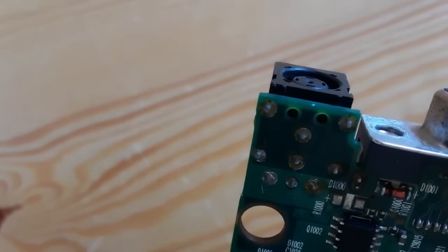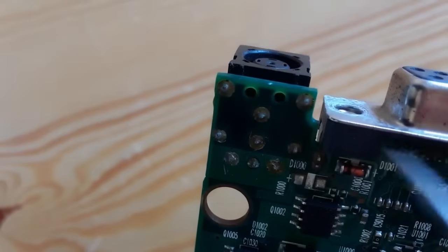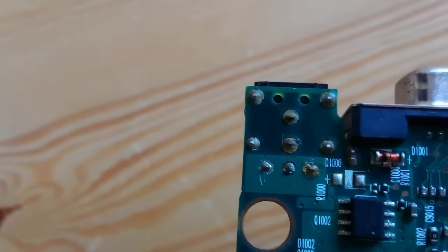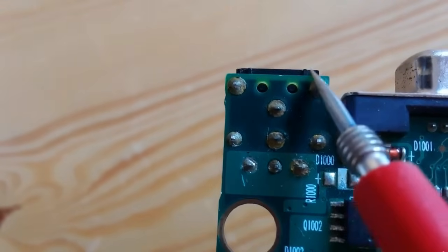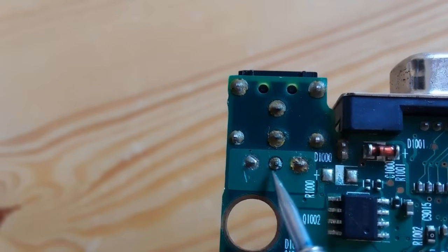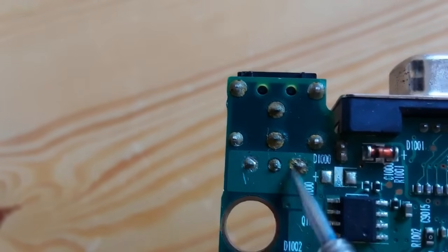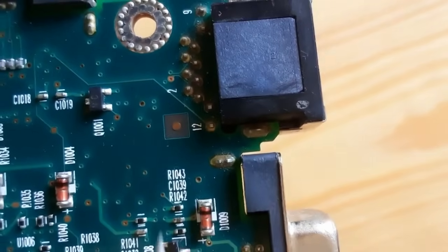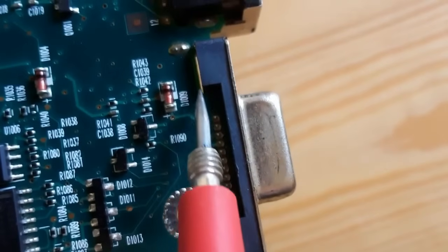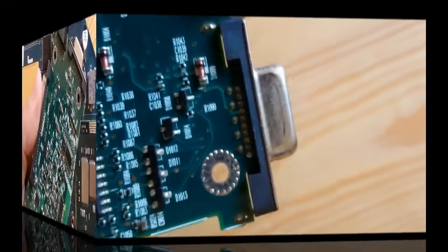in failed laptop motherboards, okay, especially for the power jack. Okay, if you have a problem or a dry solder in the power jack, the laptop or the motherboard will be a dead motherboard. You cannot get any power, no light in the motherboard or in the laptop. So that's why you should check the soldering in the terminals, especially for the power jack, of course, and for other ports.